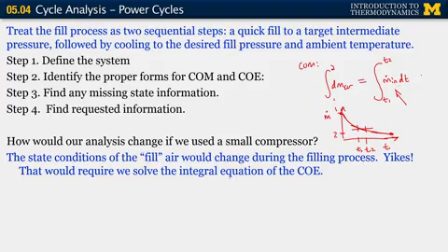Now, the next step would be to consider the conservation of energy, which is also affected by a non-steady state condition within the fill chamber. So remember before, we said during the fill process that the change in the internal energy in the control volume was balanced by the enthalpy from the fill chamber and the mass flow rate in.